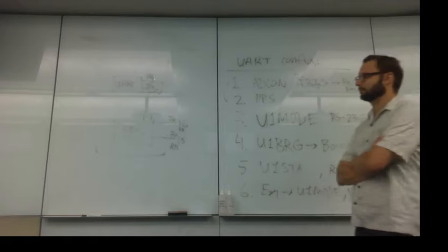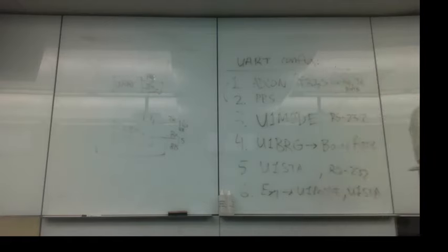And then for interrupts, it's another bunch of steps. You have to make sure that the global interrupts are enabled and the correct priority is set. And then you enable the specific interrupts related to sending and receiving. In the discussion section, we just did one function as an interrupt, and the other one we just implemented manually without interrupts. Anything else we would need to do? I think that's it.